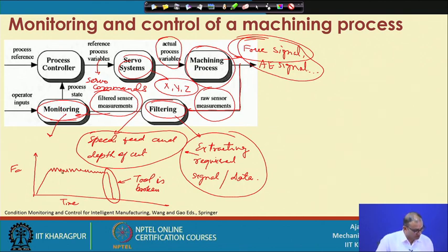Now, if you tell the system that if your force is going below a certain level, so this you consider a threshold value. Now, suppose it is a closed loop kind of thing, then you provide one program in such a way that, if the force is reducing below this particular threshold value, then stop machining. So, in that case you can actually reduce the unwanted time here, because if you do not give this, your machining will still continue, but there is no contact between the cutting tool and workpiece, and all the time will be wasted at the later stage.